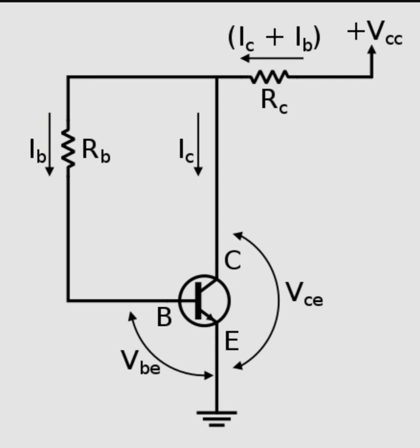So as I said, RB and RC set the operating point of the circuit. There are two ways the operating point can be changed, and we see if and how this circuit can be used to stabilize that operating point, because we don't want any variation once the operating point of the circuit is set. The first reason the operating point can change is a rise in temperature. For a fixed VBE, if the temperature of the circuit rises, the collector current will start to increase.